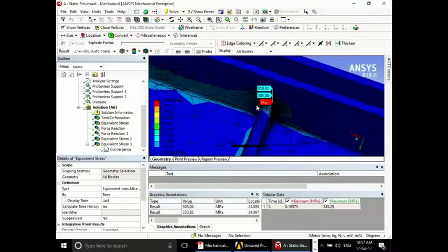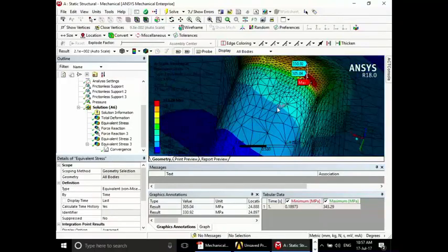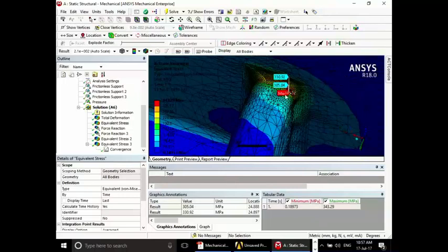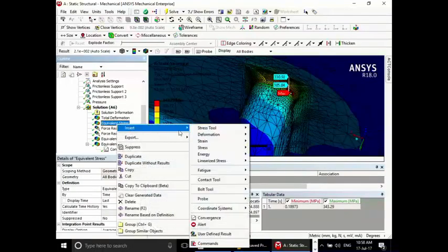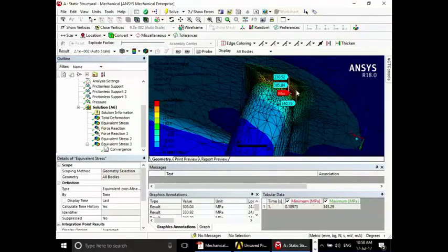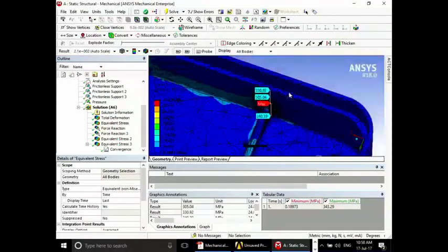Certainly in a case like this, if you did try to do that, you would wind up picking up a stress singularity somewhere. So you can do this convergence on a global result, but it's generally not recommended because it will always pick up a stress singularity, and there will always be one somewhere on your model, either because of the way it's been supported or because of a simplification to the geometry that you've made.